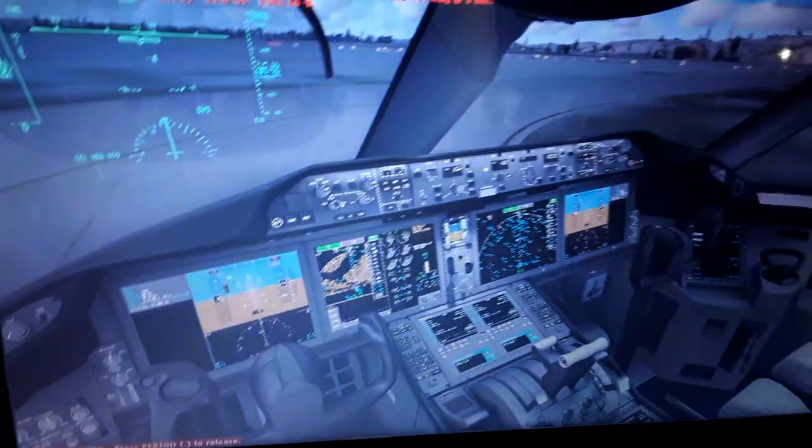You can see the runways we're gonna use for takeoff and for landing and the taxiways, the runway length and the runway heading and other information. Also we have the navigation aids, the navaids, which are the VORs, ADFs and DMEs. Also the waypoints, which are horizontal and vertical navigation fixes and altitude and speed constraints.